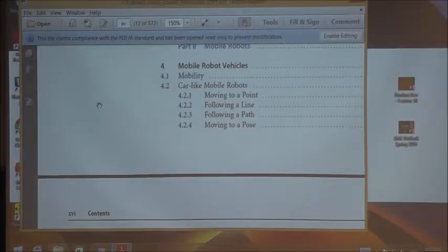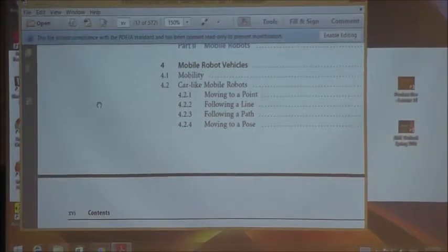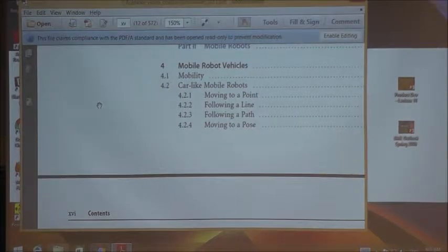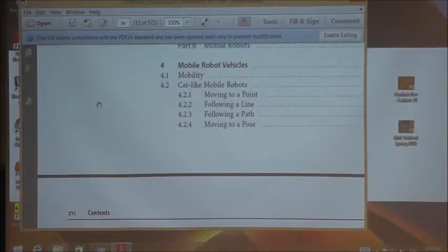Now, before we started, as you recall, Bharat was talking about you going to experiment 3 and measure the odometry error. When you want to measure odometry error, make a rough estimate of the center of gravity of the Pioneer robot on the floor, and then go from there to the designated destination.